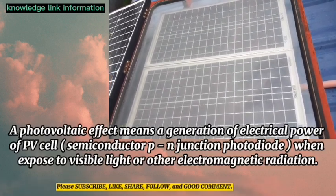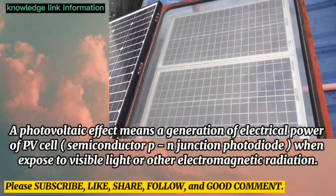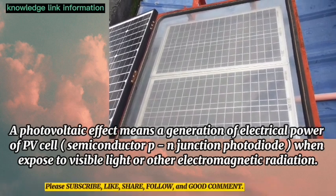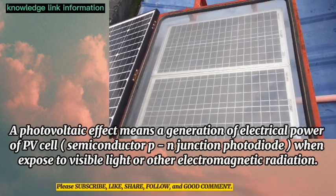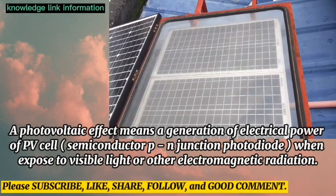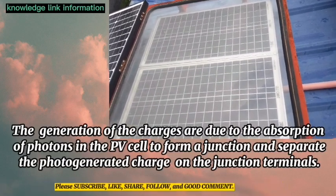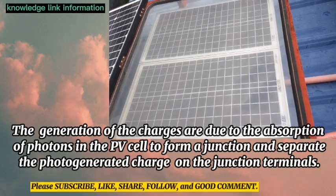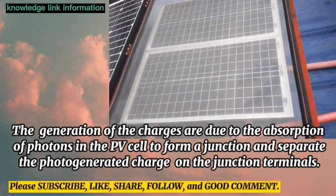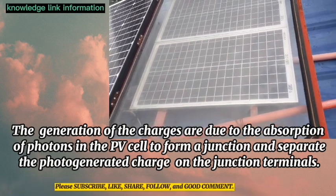The photovoltaic effect means the generation of electrical power in a PV cell, a semiconductor P-N junction photodiode, when exposed to visible light or other electromagnetic radiation. The generation of the charges is due to the absorption of photons in the PV cell to form a junction and separate the photo-generated charges on the junction terminals.